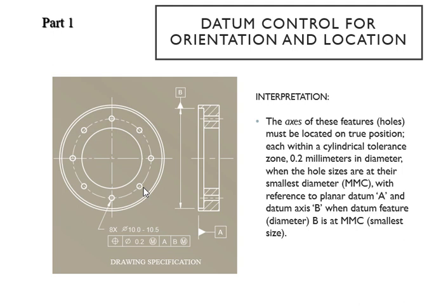Okay, so when you look at your drawing, these things are going to come into your head right away just by looking at it. Yes, you know the control frame, you know the datum feature right there. You've got 2 of them. Primary, you don't have to worry about any of it because there's no other description about it, just A. B has the MMC with it, so you know that this hole right there has to be the smallest because you want more material on your part.